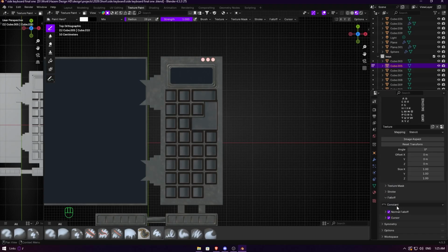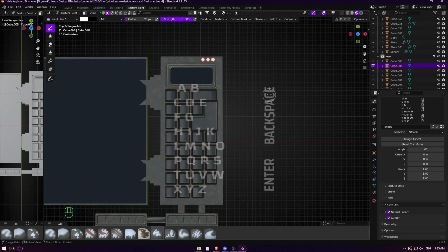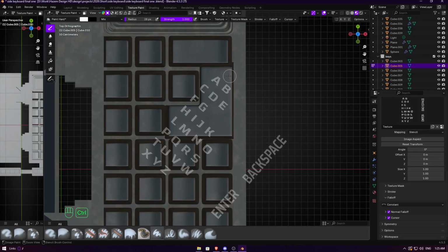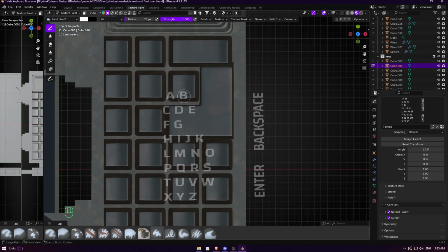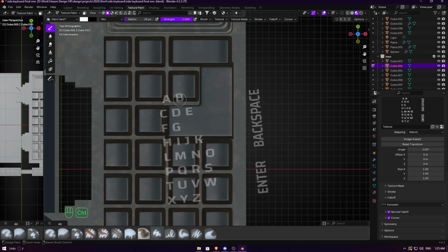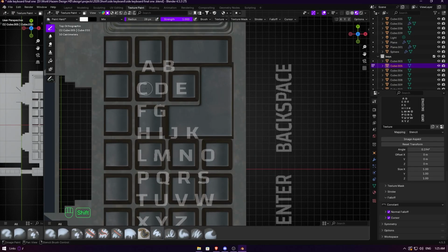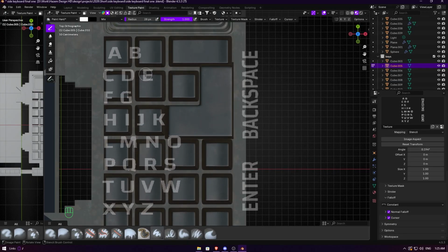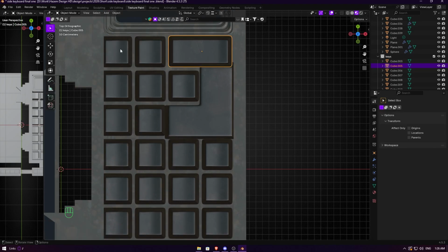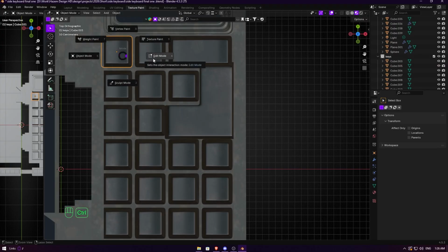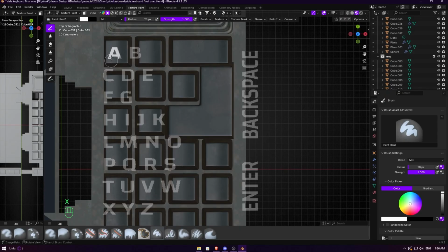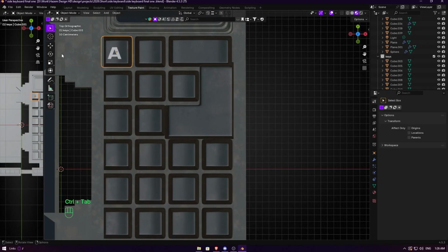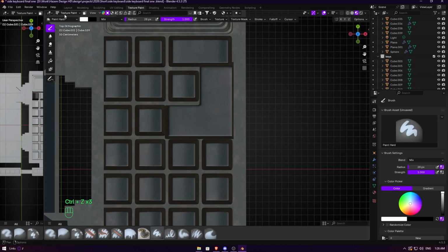contrast like this. And now you can move it with right click, rotate it with control and right click, or scale it with shift and right click. And for move, just move it with right click. And you can go here and paint over it, but it has no effect because you need to go with control tab to object mode and select your object here, and go back with control and tab to texture mode, and then start painting.